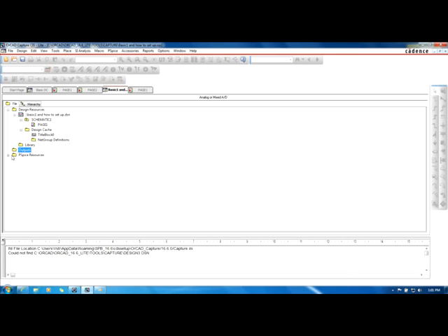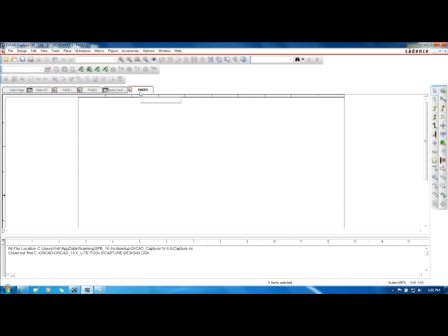So if you were going to send this to somebody, you might want to send the outputs. And actually, resources, they'll have something there too. The .net is the file that has the probes and stuff. So once you send that to somebody with that .dsn, the .net will generate on their computer whatever it needs to be when they start running things.